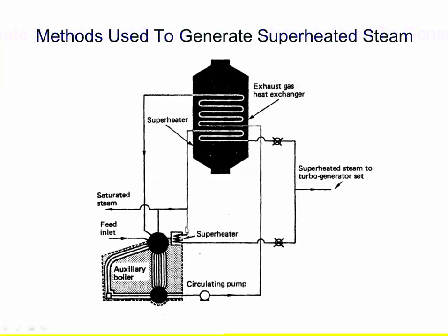You're not going to get the highest superheat temperature. That's going to decrease the efficiency of the steam turbines. And you don't have an economizer now, so that's going to decrease the efficiency of the entire plant. This is going to cost the company some money. They do this because they're so worried about whether their operators are properly trained. So think about that one.